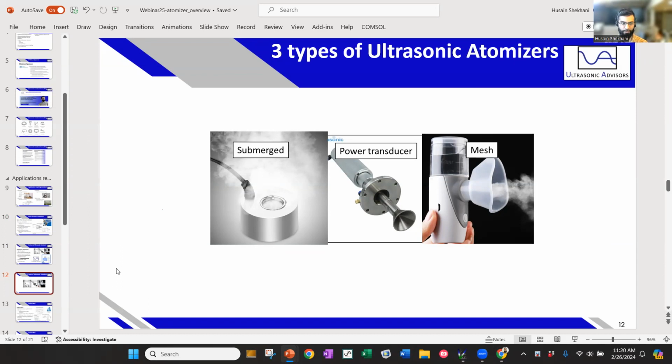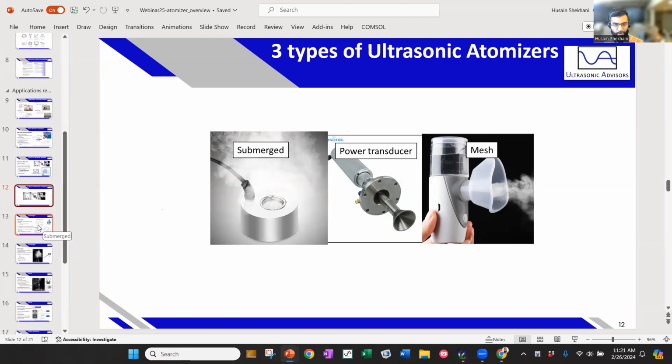Turning a liquid into particles doesn't require a lot of power for that process to happen. Unlike ultrasonic welding, for example, which is really well known for having high power devices, up to kilowatts, or usually starting in the hundreds of watts, typically 100 watts for those types of transducers. But for these cases, the purpose is to get liquid to become mist, and by driving more power into the system, you're causing more irregularity and more performance degradation in terms of your particle size distribution, rather than just improving how well it works. Oftentimes they're not actually high power requirements, but you can use them in serial.